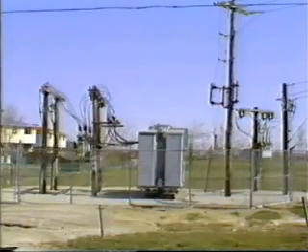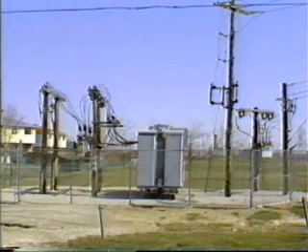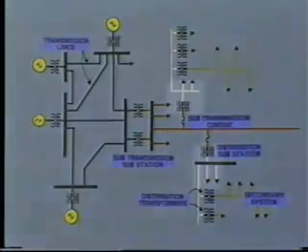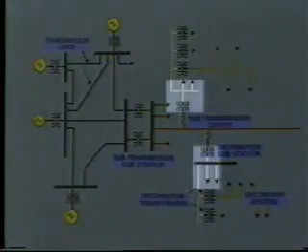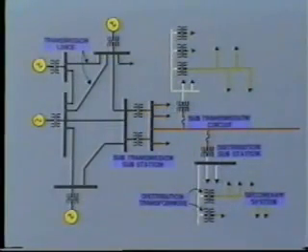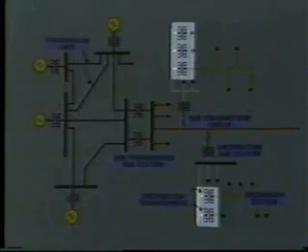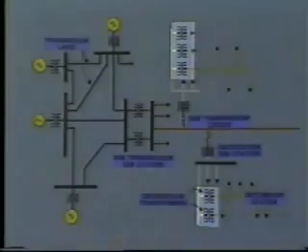In our last tape, we discussed the construction and operation of substation transformers. These transformers step down the voltage from subtransmission level to the primary feeder level. Now, as you know, one more voltage transformation is yet needed to step the primary feeder voltage down to the customer's service voltage. This is accomplished by the distribution transformer, usually located nearby the customer's premises.